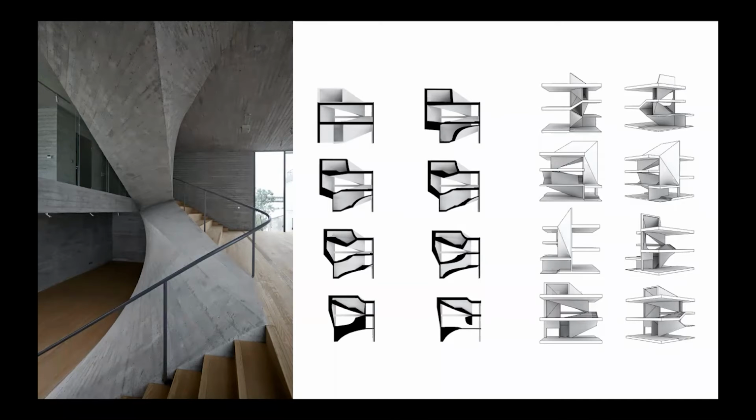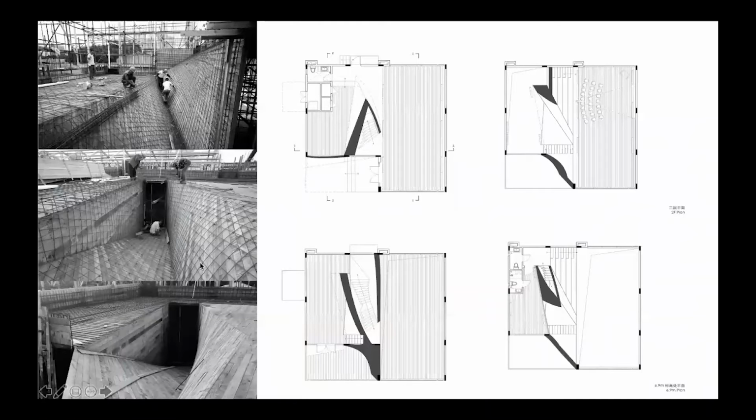And we have some special digital fabrication tools to help us address all this geometry in the construction process. We fabricated all the panels, using timber panels to generate the mold. This panel is not 100% roof surface, actually 80% roof surface, but 20% double curvature. So we needed to unfold this kind of mold, and we fabricated it with robotic timber panels and put them precisely to make the form finding of the mold, collaborating with the workers, to construct a very complicated geometry in a short time.